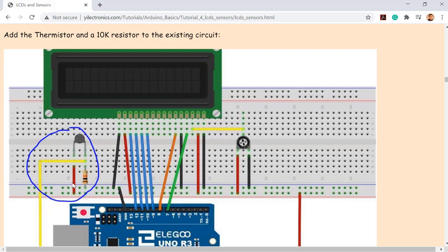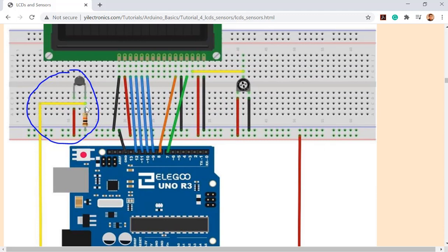That's a circuit one problem. Voltage divider. Is it a voltage divider? Okay, so when the temperature changes, the resistance here changes as well. So the voltage being sent to the microcontroller will change. So get the data.